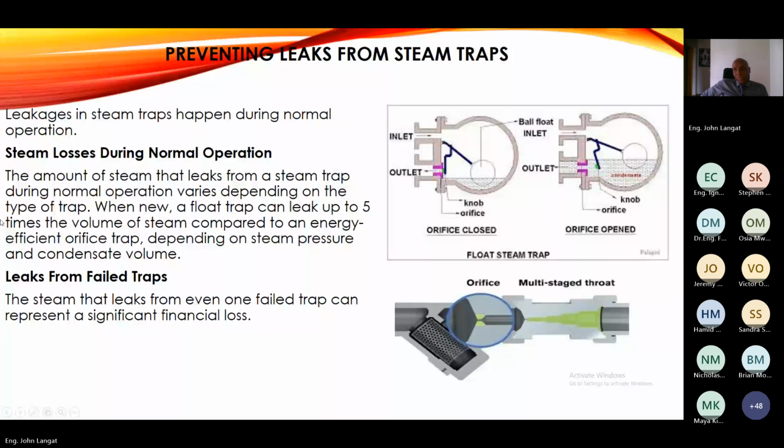Then steam traps. Also, these are leakages from steam traps. The steam trap can fail in an open mode because of debris or whatever, or the steam trap can fail in a closed position, permanently blocking the flow of water and steam downstream into the condensate line. What happens is that you'll find it bursting the gaskets and the leakages happen. So whenever you see a leakage, follow up to the trap and see if there are leakages inside the trap. If the trap fails in an open position, you should be in a position to pick that out using the thermal imaging camera, where you'll find that the temperature upstream and the temperature downstream are the same.